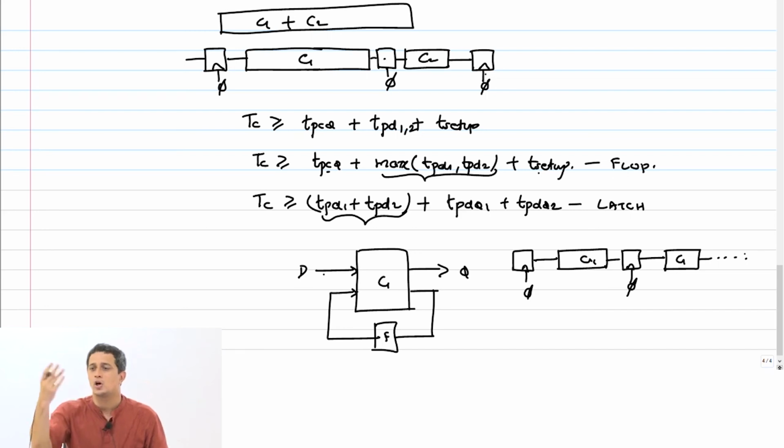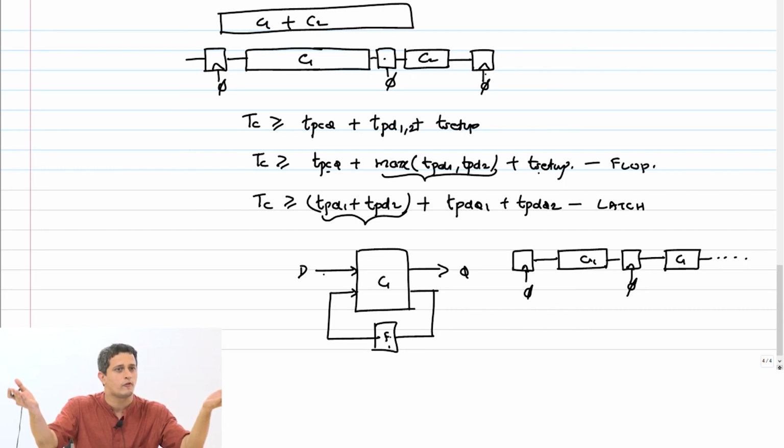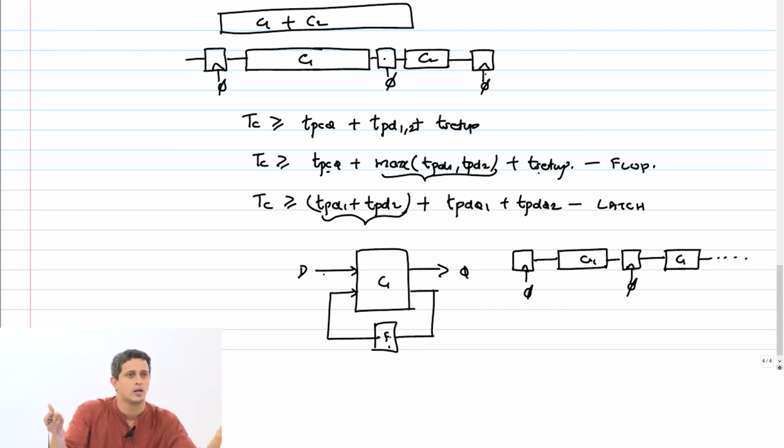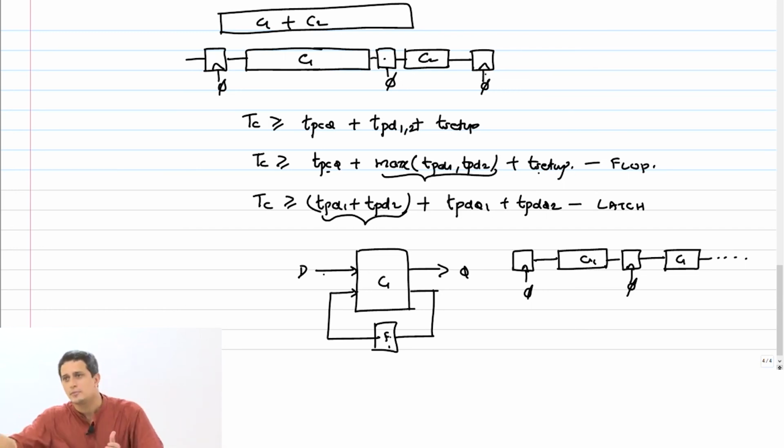But now your question is, we can come back to that question of what happens if there is clock skew. How come this system can be clock skew tolerant if I cannot borrow across a cycle? The point is the flop is the same. So there is no skew now. I can have two different flops with two different clocks and then I can talk about skew. But physically, if it's the same flop because of feedback, only in time it's getting unrolled.